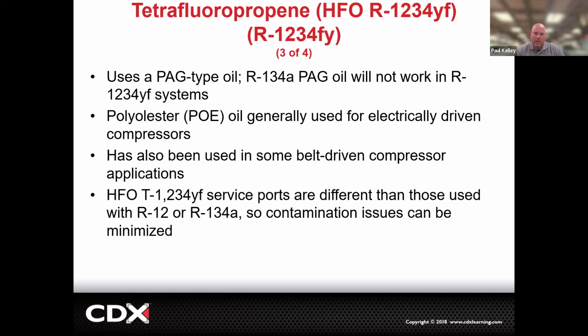Okay, but then let's say it's a hybrid or EV and it's got an electrically driven compressor. Again, that's probably going to use this polyester oil, POE oil. And then sometimes some cars will actually use the POE in a belt driven compressor. It'd be on the sticker. It'd mostly be in hybrids, but if it's on the sticker and it says POE, you need to use POE oil.